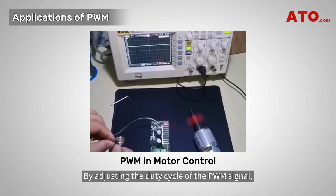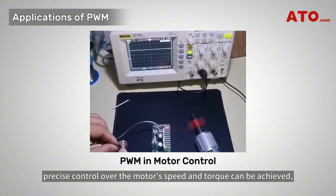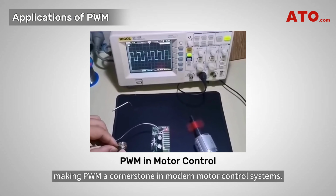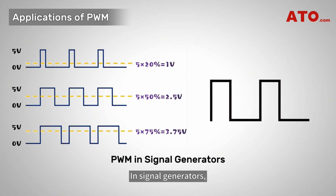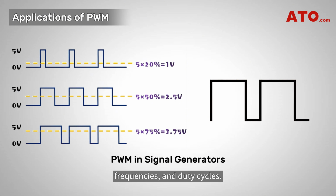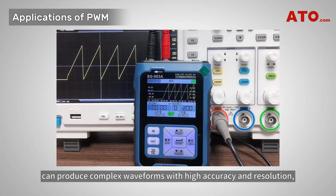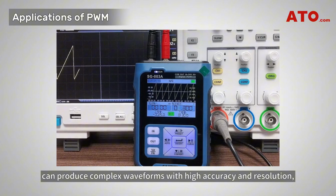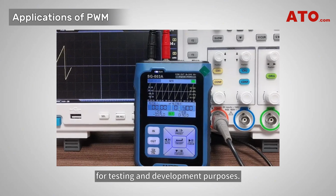By adjusting the duty cycle of the PWM signal, precise control over the motor's speed and torque can be achieved, making PWM a cornerstone in modern motor control systems. In signal generators, PWM is utilized to generate digital signals with varying pulse widths, frequencies, and duty cycles. Signal generators equipped with PWM functionality can produce complex waveforms with high accuracy and resolution, enabling engineers and technicians to simulate a wide range of signals for testing and development purposes.